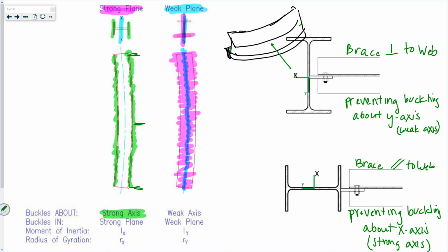So that's an example of how it can be braced against buckling. And sometimes it might be braced because generally the radius of gyration in the weak axis is less, and therefore it is more slender and more likely to buckle in the weak axis. So maybe they'll put bracing in for the weak axis buckling. And now you have different brace lengths for your x-axis and your y-axis, and maybe now strong axis buckling might occur before weak axis buckling.